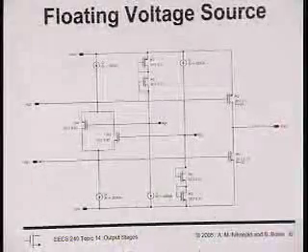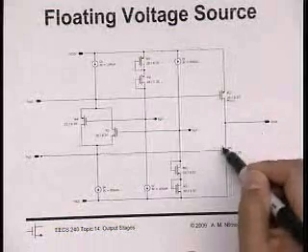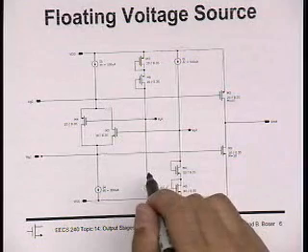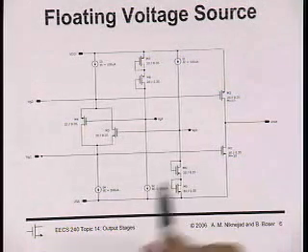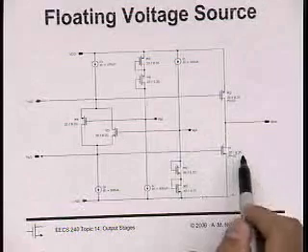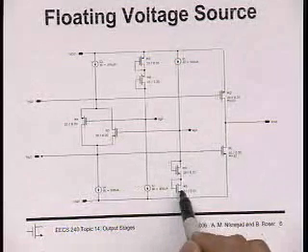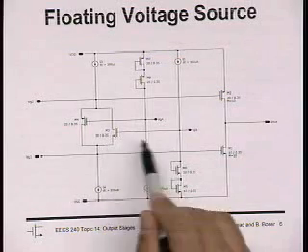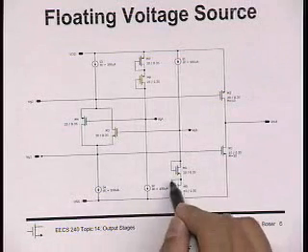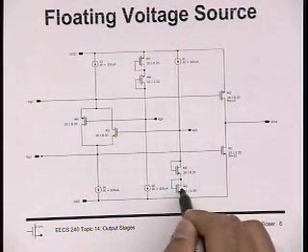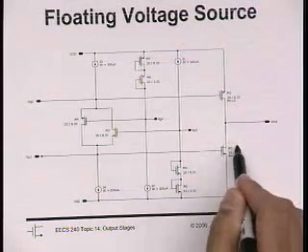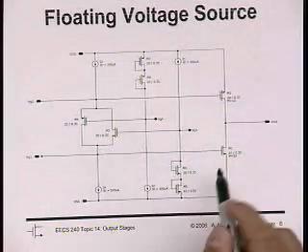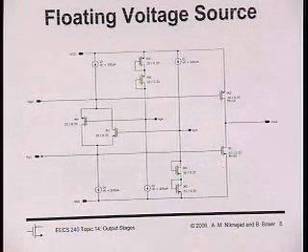But here's the circuit. The output stage is, again, common source stages, NMOS and PMOS, class AB. And this circuit actually is very similar to what we just drew. Let's look at how M1 is biased. M1 is biased through 1 VGS, 2 VGS, minus a VGS. So overall, just 1 VGS. And so if I match this device to this device, by controlling the current in this device, I can control the current in this device. Of course, these two devices have to also be matched. So this device is biased up correctly.